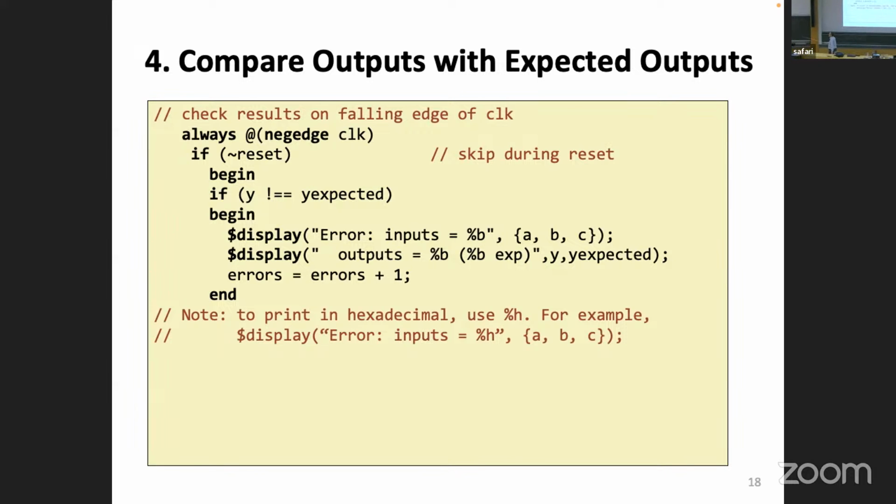And just to make my life easier, I realized that there will be this falling edge event, and we say, let us sample the outputs at the falling edge. This is because we are lazy, and because we don't want to do too much complicated programming and enter an arbitrary delay. We realize that sometime it's going to fall. And this is why we say always at negative edge. Why not?